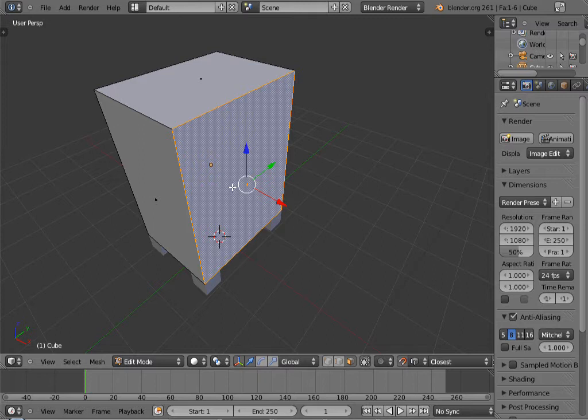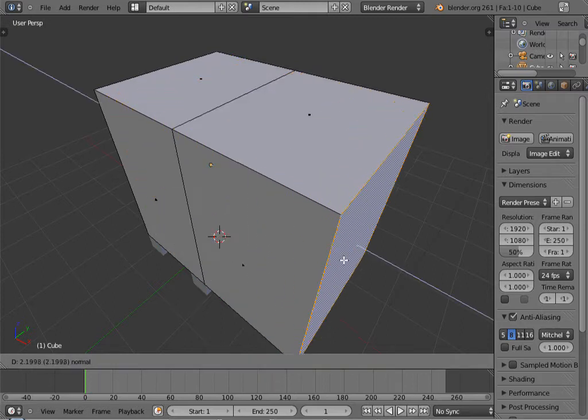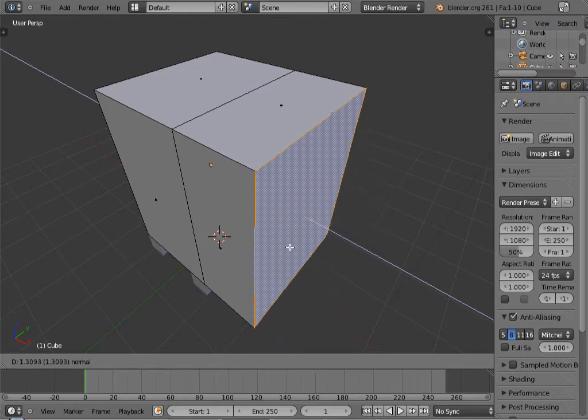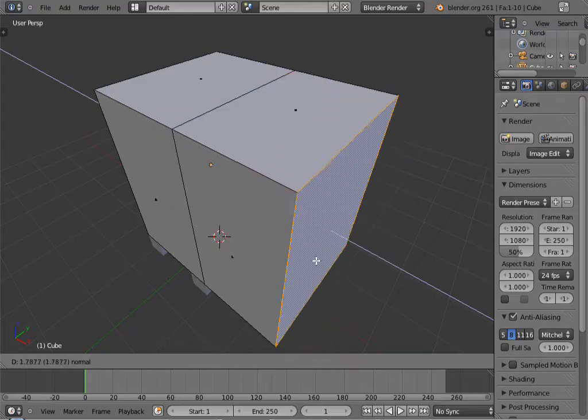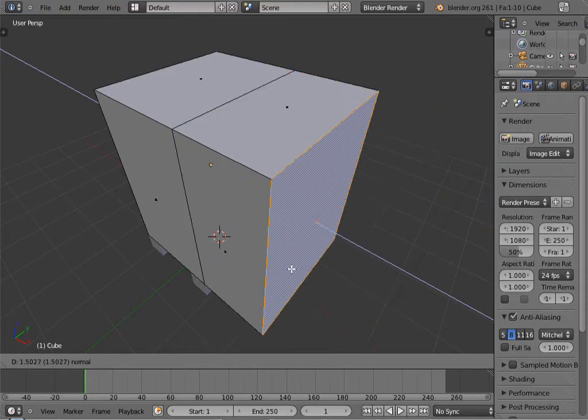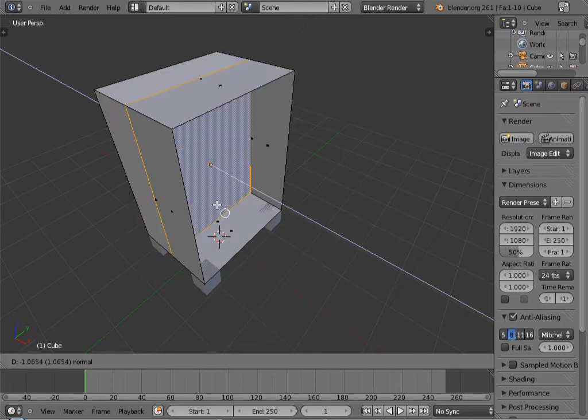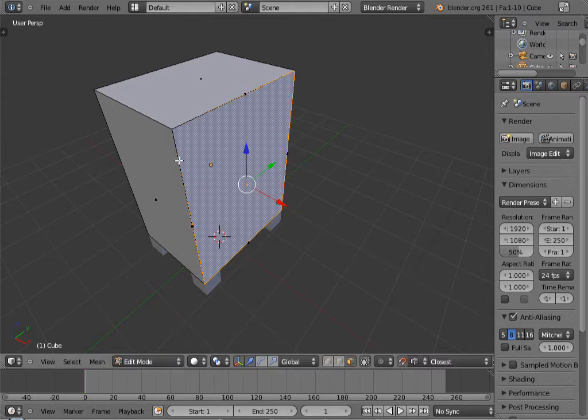But just to show you what an extrusion is, I'm going to press E, and I've still got snapping on. That doesn't matter. But you can see basically it extrudes out. You can also extrude in, or intrude if you like. But it's actually handy that I've got edge snapping on, because what I'm doing here by creating an extrusion that has no length, I'm creating... I'll click left there to create that.